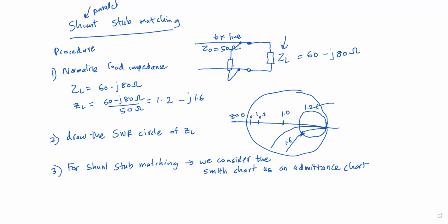So the impedance and the stub will be in parallel to each other, right? Once we are going to match these two impedances, we want to take the sum impedance. Rather than taking the impedances themselves, once we take the admittance value of these impedances, we can directly add these values. Now, if the admittance of this impedance is YL and the admittance of this stub is, let's say, YS, we need to add these YL and YS and get some real value as the output, right?